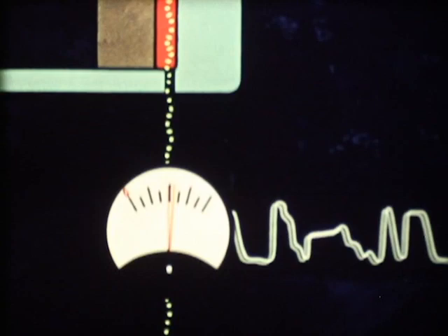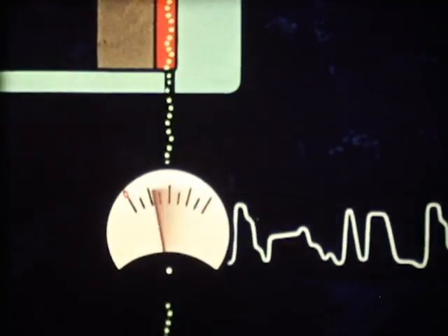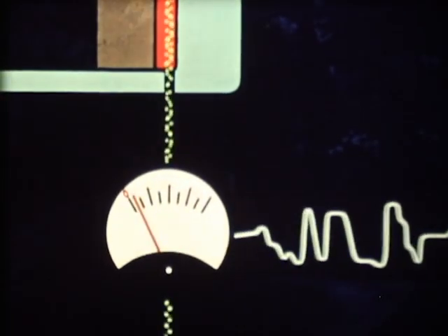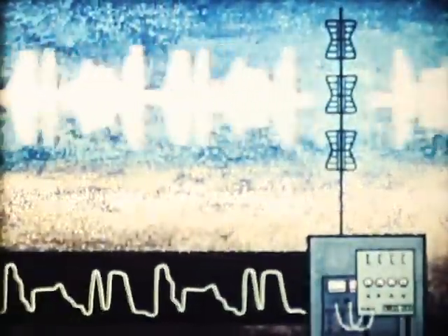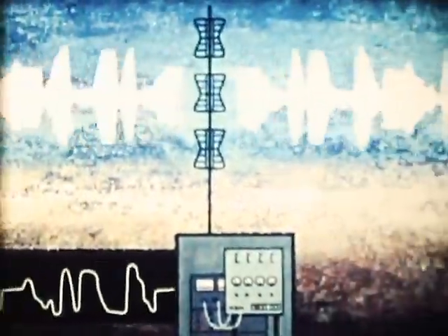This scanning process goes on repeatedly, line after line and picture after picture, producing an uninterrupted series of charge impulses which, due to their amplitude differences, carry all the picture information. The television picture signal formed in this way is sent out by the transmitter, detected by the receivers, and finally converted into a luminous, live television picture.